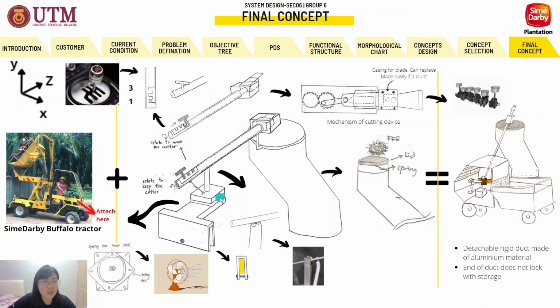Next, moving up to the device, there will be one rotating swivel mechanism to allow the whole device to turn left and right like the motion of this fan. The mechanism will have one fixed plate mounted onto the fixed platform and one turning plate as shown in here. This will allow the worker to have more control of the cutting motion.